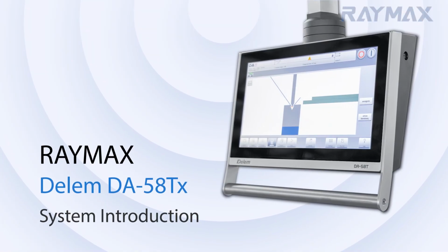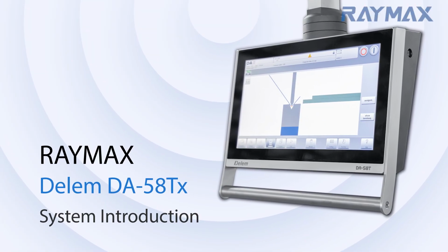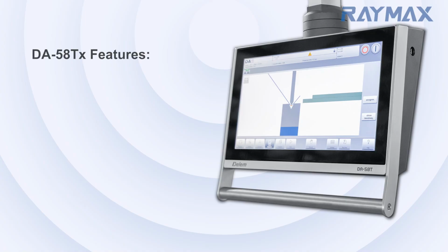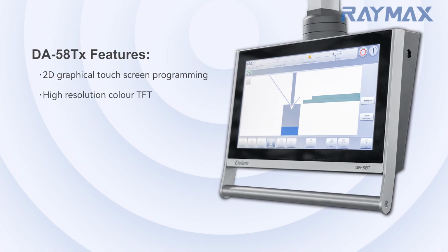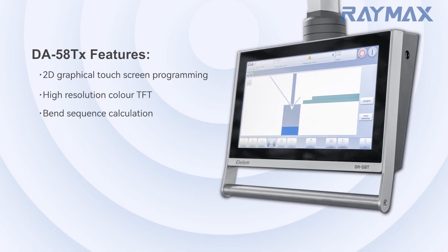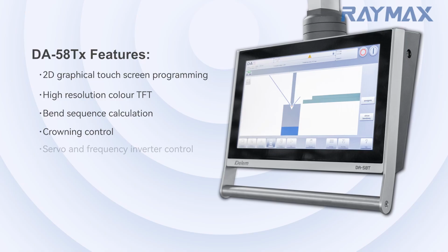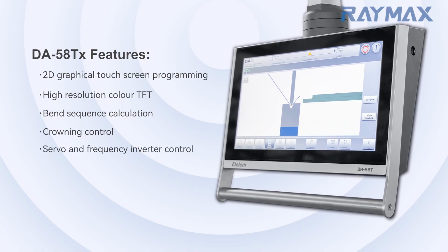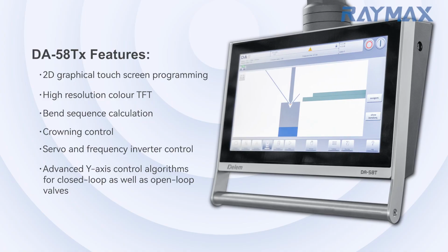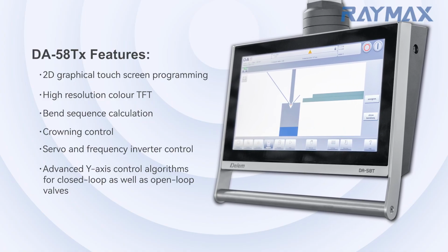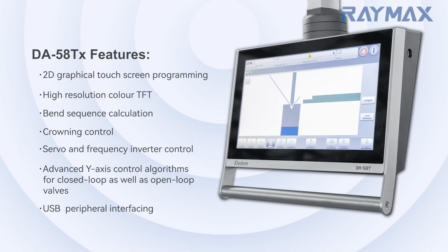DELEM DA58Tx. System Introduction. DA58Tx features 2D graphical touchscreen programming, high-resolution color TFT, bend sequence calculation, crowning control, servo and frequency inverter control, advanced Y-axis control algorithms, for closed loop as well as open loop, valves, USB peripheral interfacing.